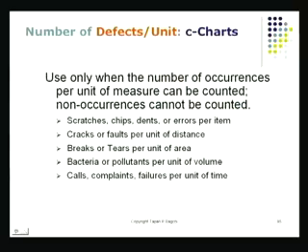The case was there, but when I tried to put it back together again, it did not fit very well. That would be a defect. So there could be multiple defects on one item. If there are multiple possibilities of defects on an item, what I do is I construct this C chart. The C chart is also a count. It again has its own control limits, and I'll show you the formulas for it.